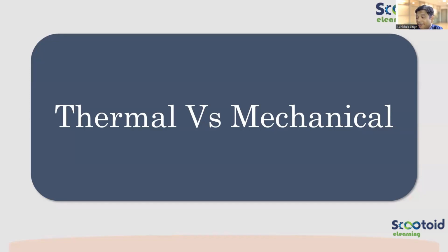They will decide what design pressure is required, what the temperature is for that reaction to happen, that heat transfer to happen. In this case, it's heat transfer. So to maximize the heat transfer, what is my good pressure and temperature? Based on the flow coming to that heat exchanger, what should be the size? Even the size is decided by process, the chemical engineer. Making sense, guys? The sizing of that heat exchanger.